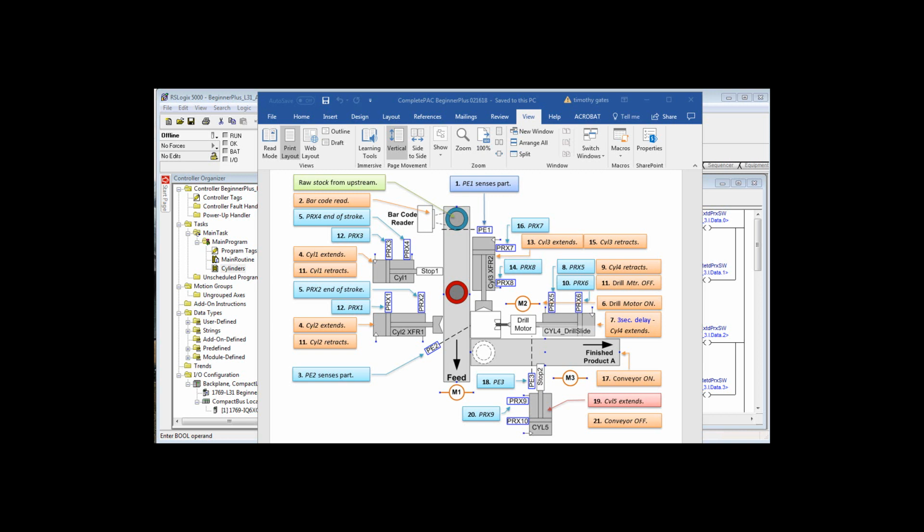Because we're not going to do anything until we sense, in the case of cylinder 1, the stop being all the way out there, that's not a huge concern. But cylinder 2 fully extended is pushing the part into that workspace against a V-block, on the other side of which is a drill motor with a drill bit, or a drill as they say.